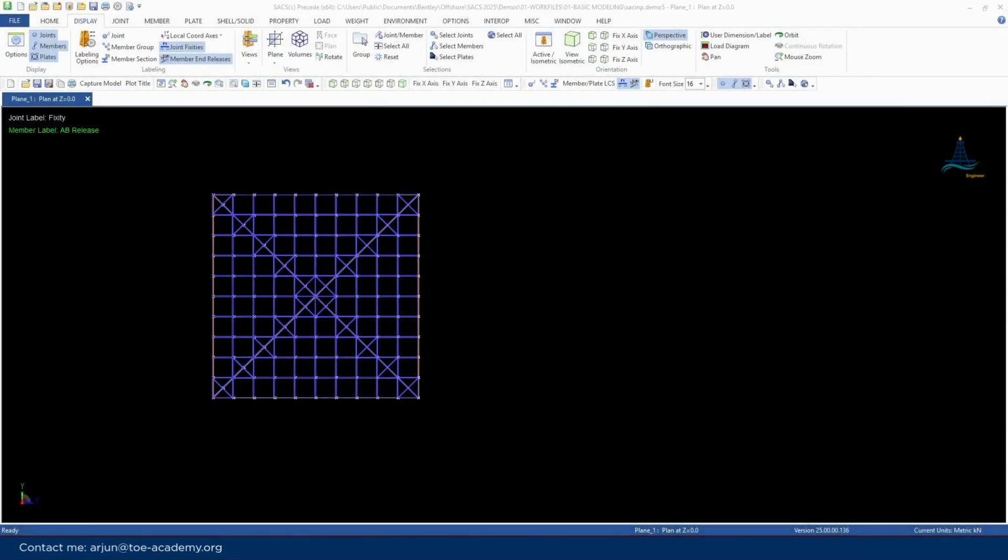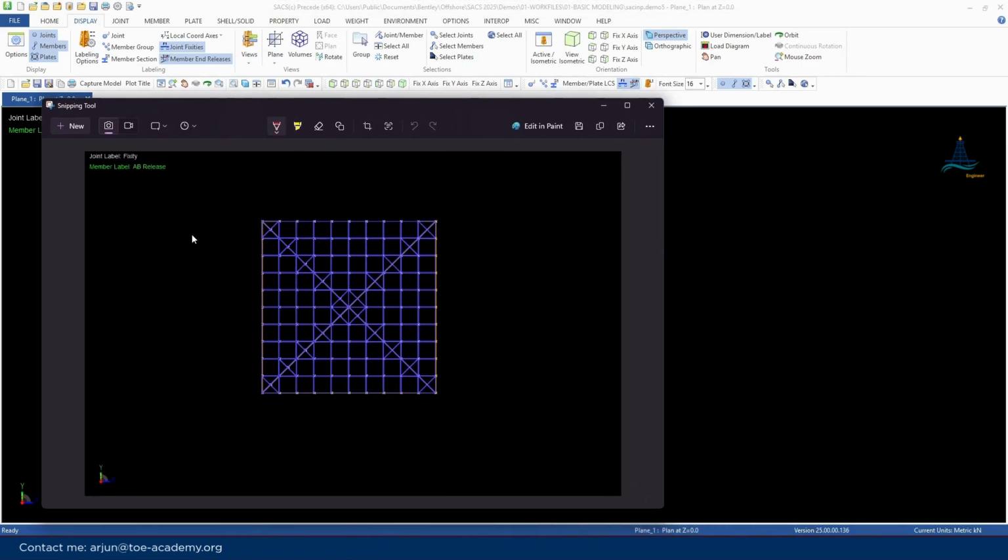So we have two options to give the spring constants. Either we can provide XY at any diagonal corners, or you can provide only stiffness for x here, only for y here, and at these corners for x and y.